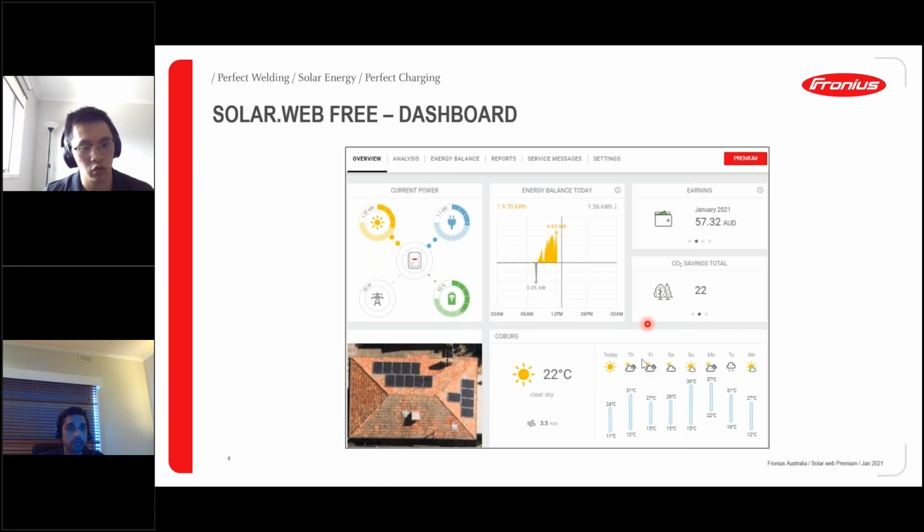There's a question, I'm not 100% sure what you mean by that, but you said, how can we change the voltages if we want for grid fault? If you need to change grid settings of the inverter, you need to contact our PV support guys. They will give you a code to allow you to change the settings. But again, you need to check with the DNSP if you're allowed to do it.